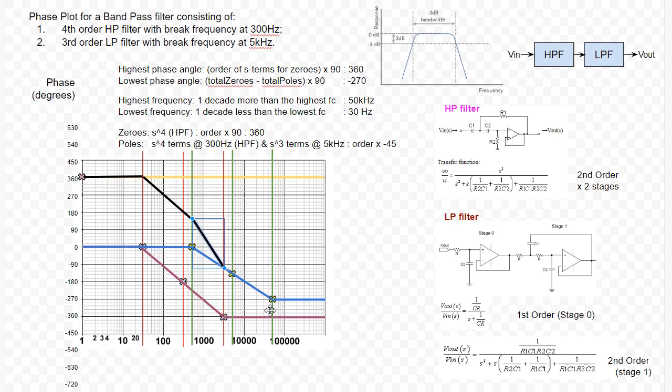All right. And then from here to here, that means from 3 kilohertz to 5 kilohertz. Now this is 0, this is 0, this is the only one that is left, and it is at negative 135. So therefore, you're going to have a little kink there.